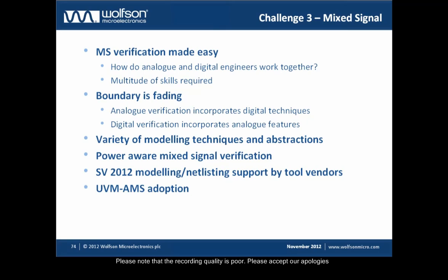And the third challenge is about mixed signal. Hence, Wolfson has always been a strong mixed signal company with analog ADC stacks and all sorts of stuff on the chip. Mixed signal has become more advanced over the past few years, and there are quite a few modern digital techniques emerging on the market, which I quite like to see. So you've got this variety of abstraction techniques now, beginning with real number modeling, or Verilog-AMS, or VHDL-AMS. Maybe you can even apply emulation once you have everything in the digital world.